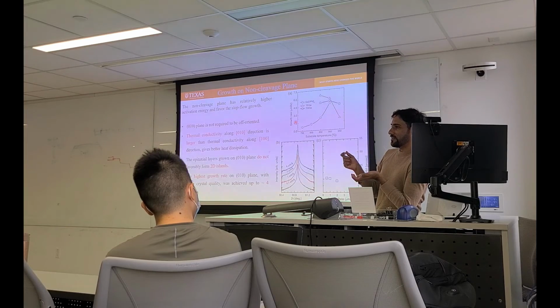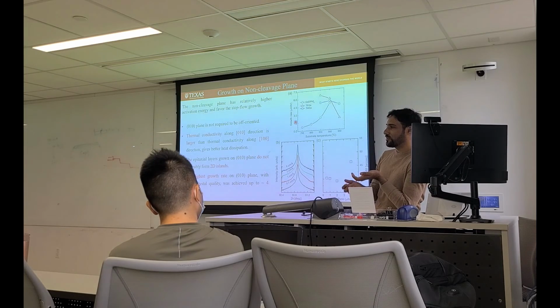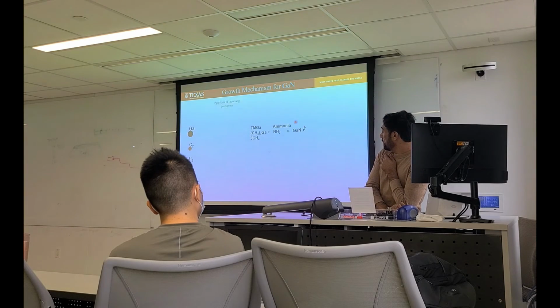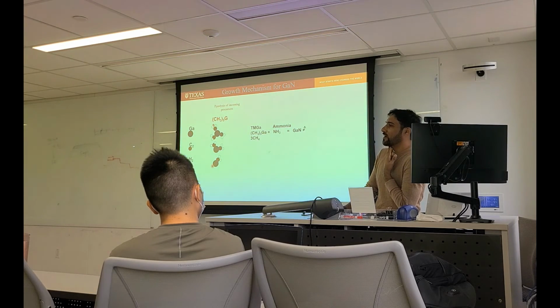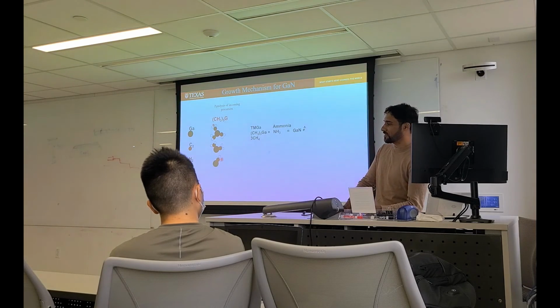If it doesn't dissociate, it can go to the exhaust, or it can create defects on your substrate, like impurities. So trimethyl gallium is well studied. If we compare trimethyl gallium with triethyl gallium, triethyl gallium gives higher carbon contamination. Monomethyl gallium has a higher dissociation temperature, it does not break, and sometimes it has carbon. Sometimes it penetrates into the crystal, so you have carbon contamination.